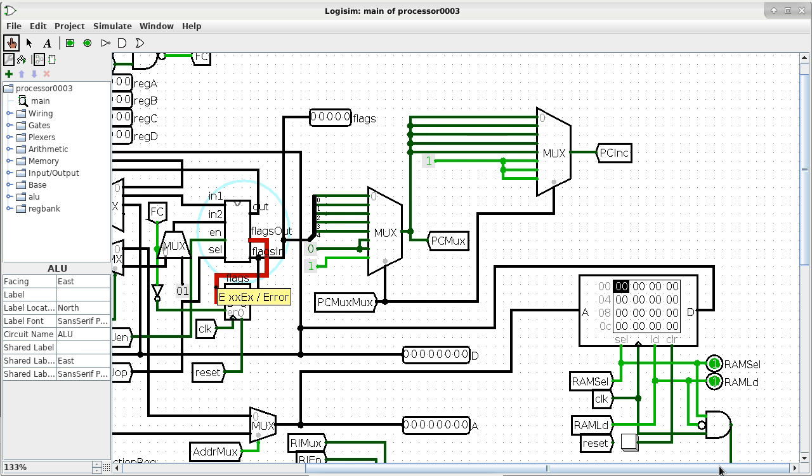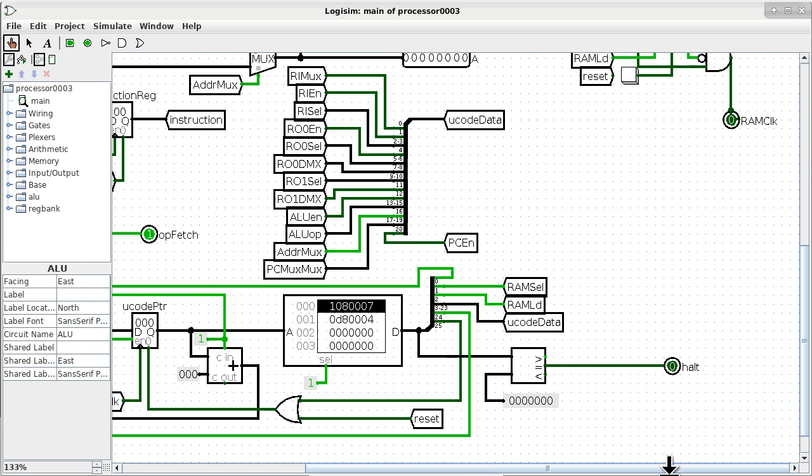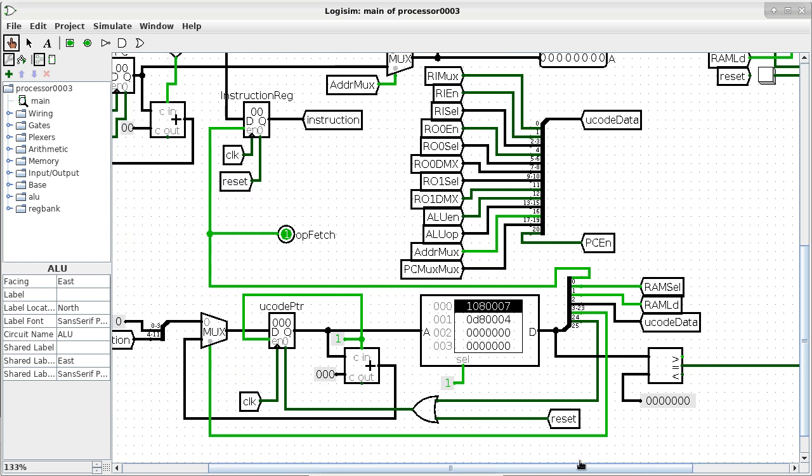Then what about that ROM down here? If the RAM is specifying what operations to perform, what is the purpose of this ROM? Whatever we store in this ROM is called microcode. I call these microcode slices. Some people just call it microcode, but I like to refer to each location as one slice of microcode.